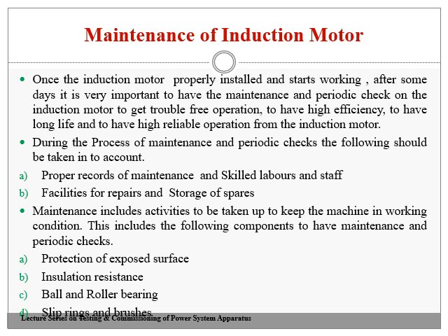It is to be done in accordance with the standards provided for the particular induction motor, or the Indian standard IS 4029. During the process of maintenance and periodic checks, the following should be taken into account. A proper record, that is a log sheet, should be maintained, the work should be conducted only with the help of skilled technical persons, and facilities should be provided properly for the storage of all the electrical equipment required for a particular maintenance.